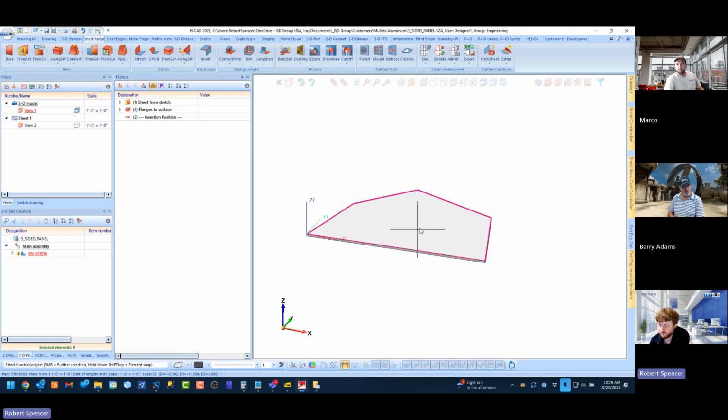Occasionally, or probably more often than not, you might have a panel system variant that works for, we'll say, 90% of the situations, but sometimes you get to something unique, just model it. Just model it in place in your model and be done with it rather than trying to spend time. I get it, I want that in my variant so that I can use one part file for all these situations.